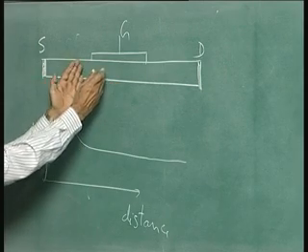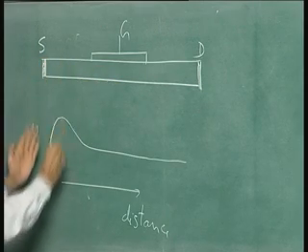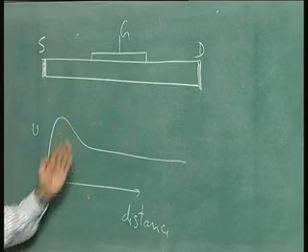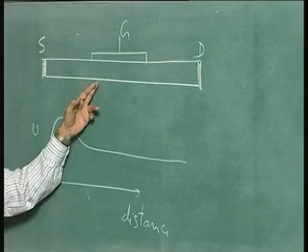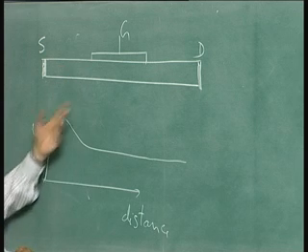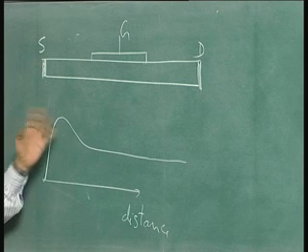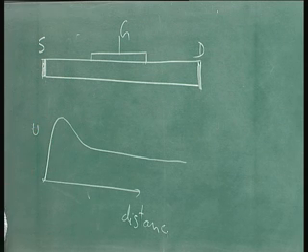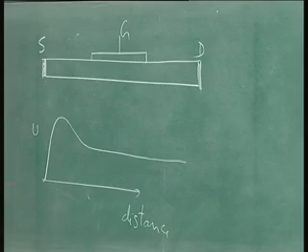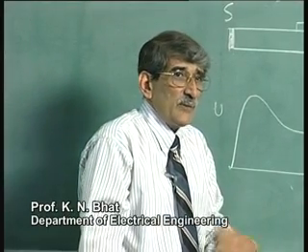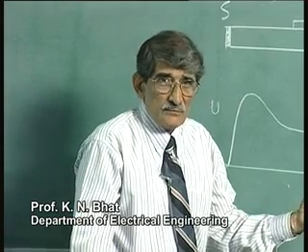Whereas, if this length is short, the overshoot effect is seen under the gate itself. That is actually the real channel where you can control everything, current flow, etc. Okay. So, you get the benefits if the channel length is shorter. You get the benefit of velocity overshoot effect. You also will get the benefit of high mobility when the field is low.